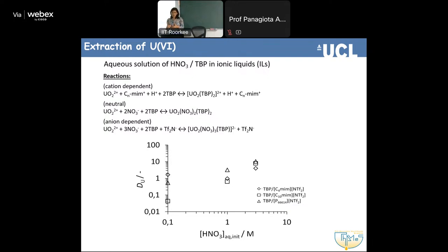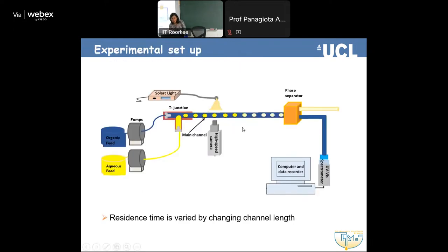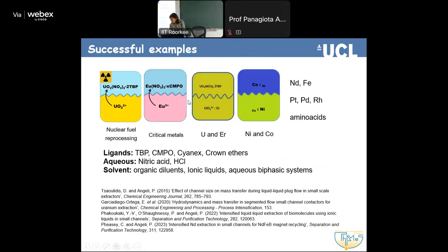What I want to bring in, though, is something that we are interested in as chemical engineers, which is the rate this happens. Once I bring together the two phases, to get the equilibrium, what we do is we have a small vessel, we put the mixer, we put the organic, we put the aqueous phase, we put the extractant, we mix. After an hour, 2 hours, 3 hours, we read the concentration here and here. So this transport doesn't happen instantaneously. It takes a bit of time.